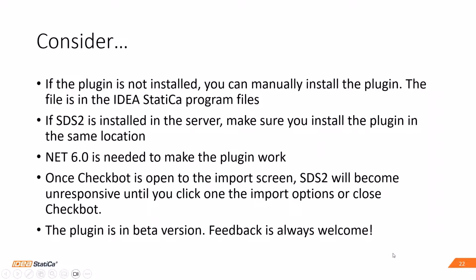There are some things to consider, as I mentioned. Of course, this plugin is an advanced beta version, all right? And we have found some things, and I am sharing these items that we have learned, all right? If the plugin is not installed and you try everything, we have the file of that plugin in the IDEA StatiCa program files. If you have this issue, just contact me and I can help you with that. Also, we have found some cases where the user has the SDS2 application installed on the server. So make sure you install the plugin in the same location, okay?